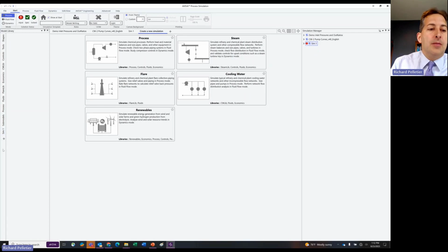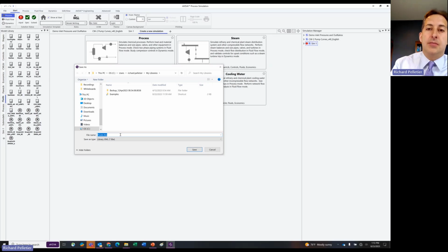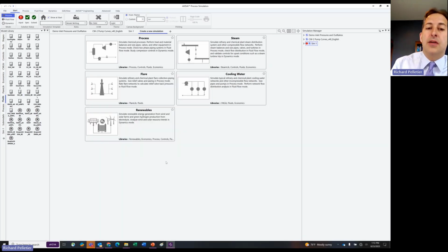All right, so you do have to remember that if you decide to use any of these additional model libraries or create your own model library, you will often have to share a custom library by exporting it to a libx and sending them the libx, or you will have to tell them, oh, I'm using the absorption library. Please import it first, and then you can use the SimX file, right? So that's a little bit about managing the libraries.